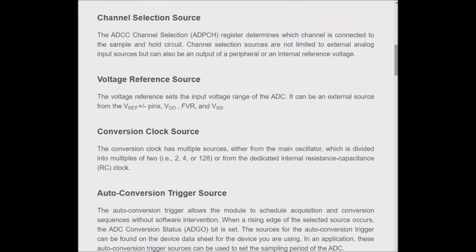Channel selection source. The ADCC channel selection ADPCH register determines which channel is connected to the sample and hold circuit. Channel selection sources are not limited to external analog input sources, but can also be an output of a peripheral or an internal reference voltage.